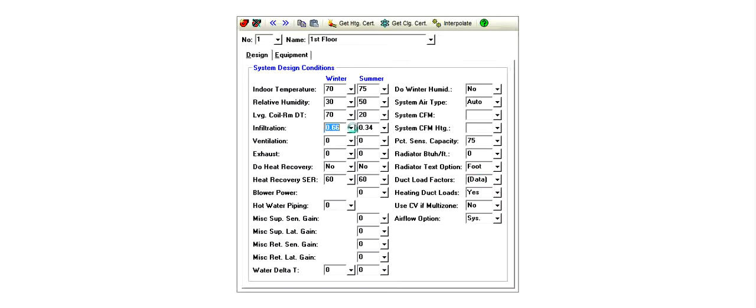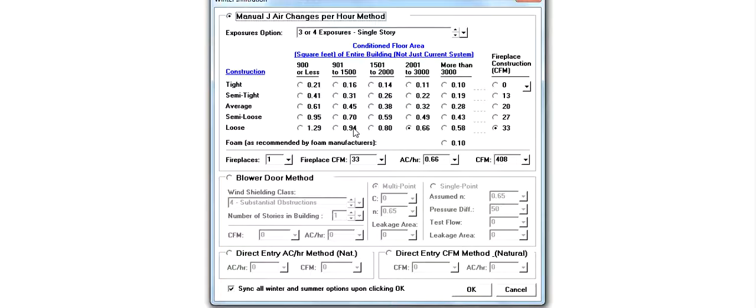We did not touch the air infiltration because, in the previous video, we saw that air infiltration doesn't offer the greatest benefit for this region. So instead of spending money to try to stop air infiltration, we spent that money on replacing the windows and conditioning the attic.